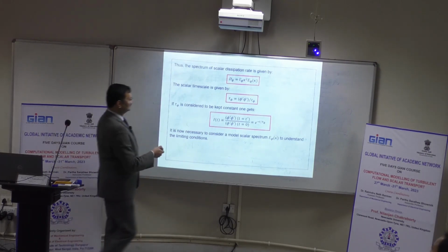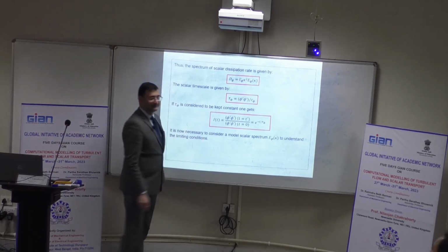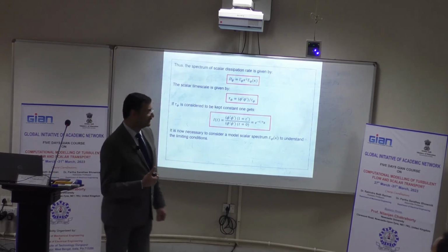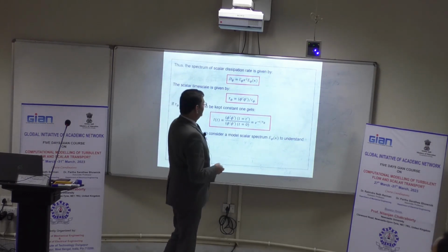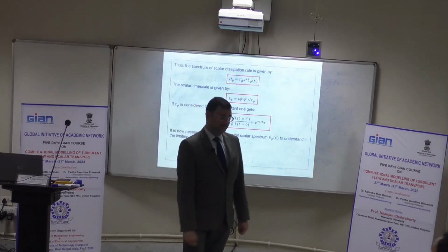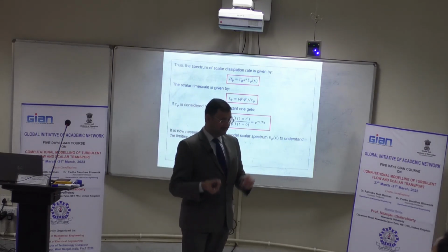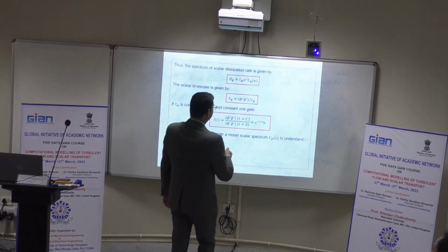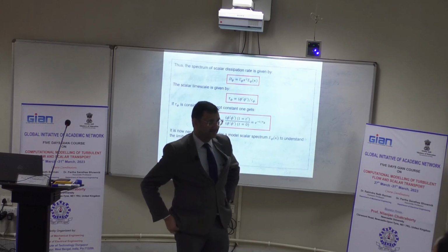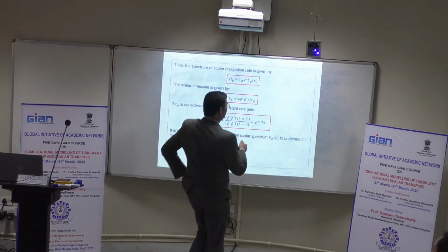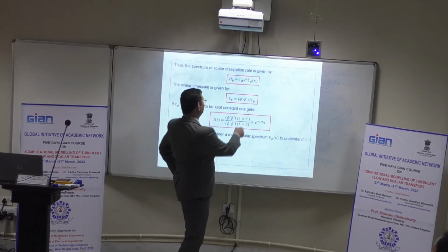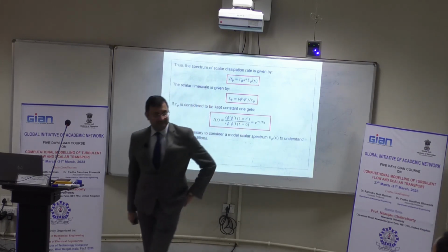The scalar time scale is defined like this. Again, similar to, if you consider, this one has no unit, right? Scalar doesn't have any unit. What's the unit of the scalar dissipation rate? 1/second, right? So 1 divided by 1/second gives you second. So this one basically gives you a measure of the time.